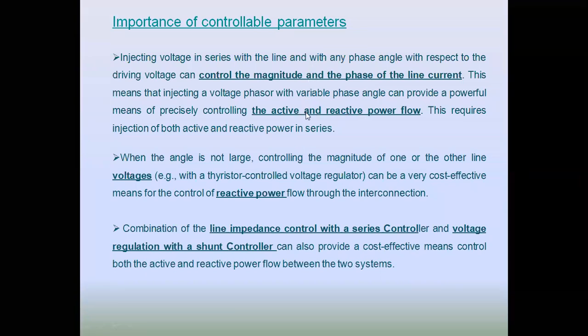In case of UPFC, we have seen that 360 degrees of control of phase angle is possible, and you can change the voltage magnitude from 0 to V maximum. That is the advantage of UPFC over the other devices. That means you can have control of real and reactive power by injecting a voltage with controllable magnitude and also phase angle.